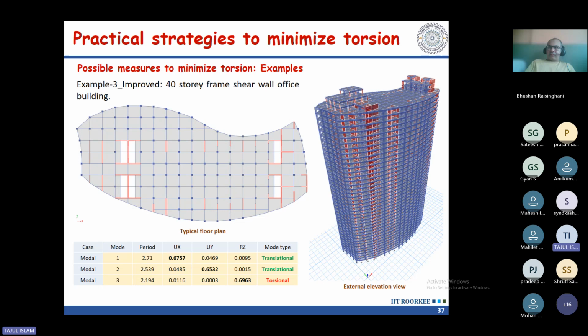If you are modeling one tower, you are ignoring the significant torsion, because torsion will happen because of that only. So you are completely ignoring that, and I don't think it is recommended. In fact, that is most important to consider in your case.